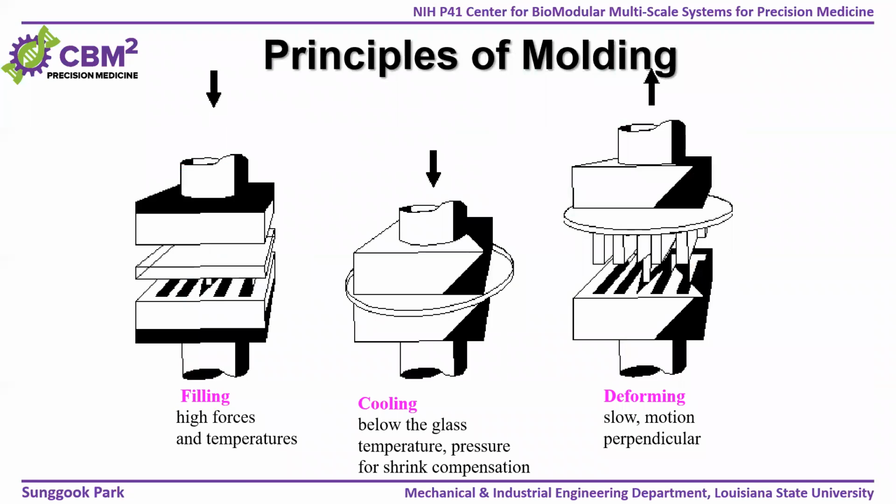Okay. So first, I'll talk about hot embossing. For hot embossing, you need a substrate. Here, normally you use a thermoplastic. We place it between two platens, and on top of one platen we put the mold insert. Then we increase the temperature and apply force.